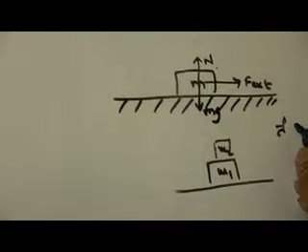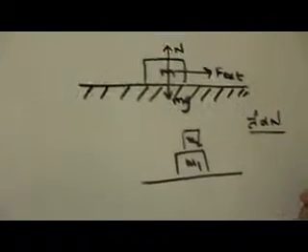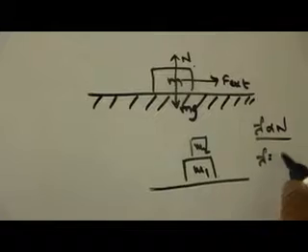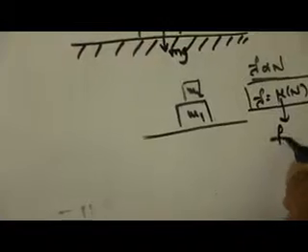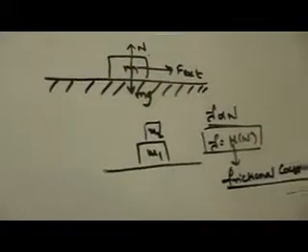So the frictional force that increases is directly proportional to the normal reaction. The proportionality constant is called mu, and this mu is called the frictional coefficient. This is of 3 types: static coefficient, kinetic coefficient, and rolling coefficient. Generally, the static coefficient will be greater than the kinetic coefficient, which is greater than the rolling coefficient. All these experimental notions will be discussed by me later.